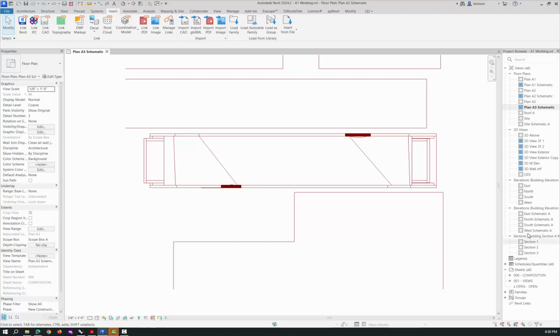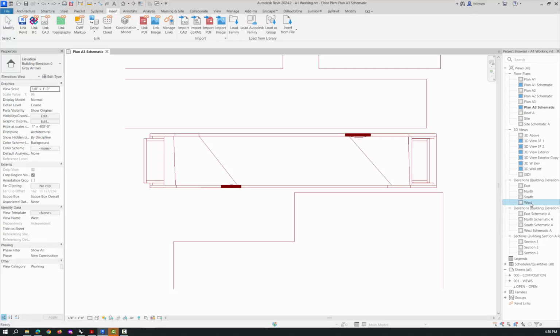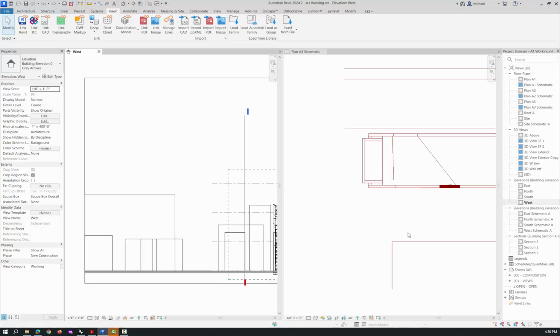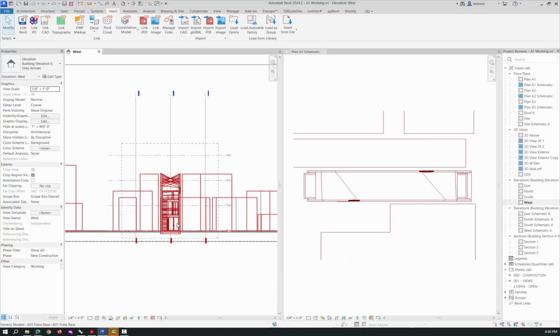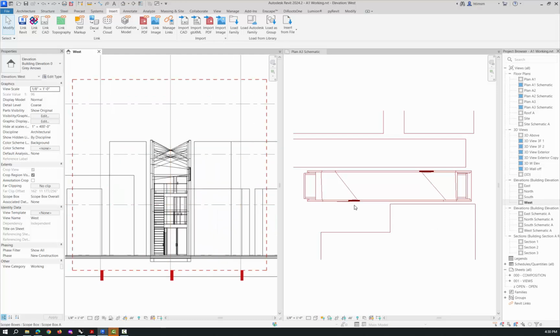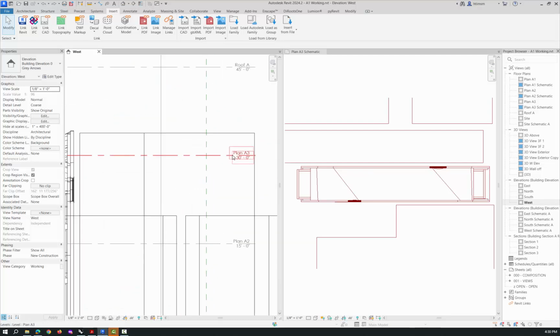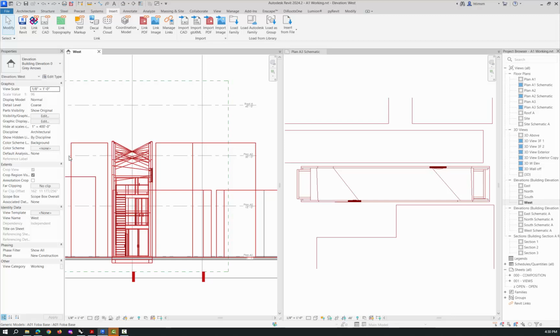And then I'm going to open up my west elevation, right? And then I'm going to do that WT, so WT for window tile, and ZA again. And I'll zoom in on my west elevation and kind of zoom in on this floor plan. So what's cutting this floor plan at level 3 is this level is a plane that gets cut all the way through the model, and it goes up 4 feet above that and cuts it. So it's just hitting the tips of the top of this model.